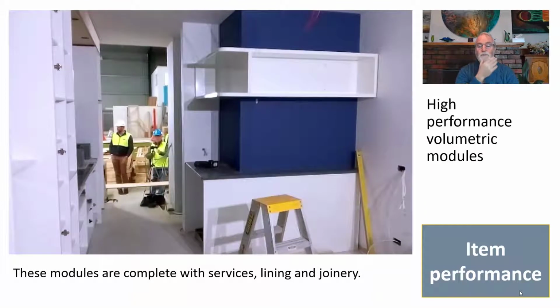This is a high performance volumetric module. So this is the inside of a module. The module itself is about 4.1 meters across on the outside. So it's about 3.85, 3.9 inside. They're completely serviced, they're lined, the joinery's in, the tiling's in, the plumbing works, and all the services are led back to a single duct, which then allows for all of them to be connected up without anyone actually coming into the module before the building's complete.